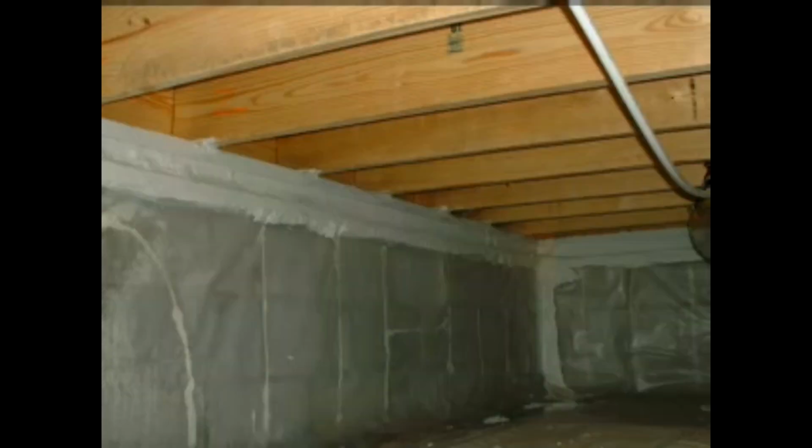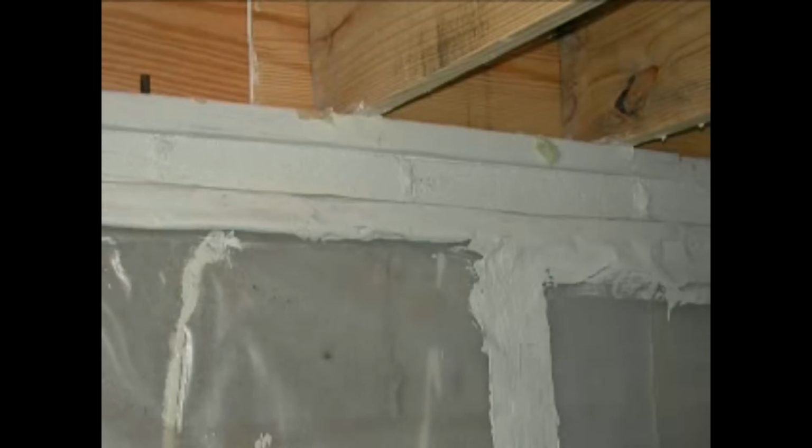In addition to the wall sealing work, we installed crawl space liners to minimize water vapor entry from the earth floor and through the masonry walls. The liners were created by extending the 6 mil ground poly up the walls. At the top edge, the wall poly stops 3 inches short of the wood sill. This provides us with a clear termite inspection strip. We use duct mastic to seal all edges and seams of the poly liner.